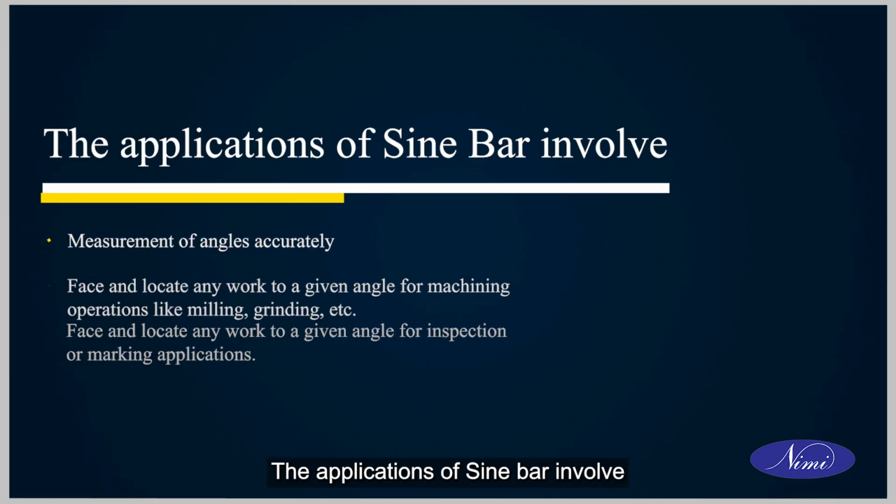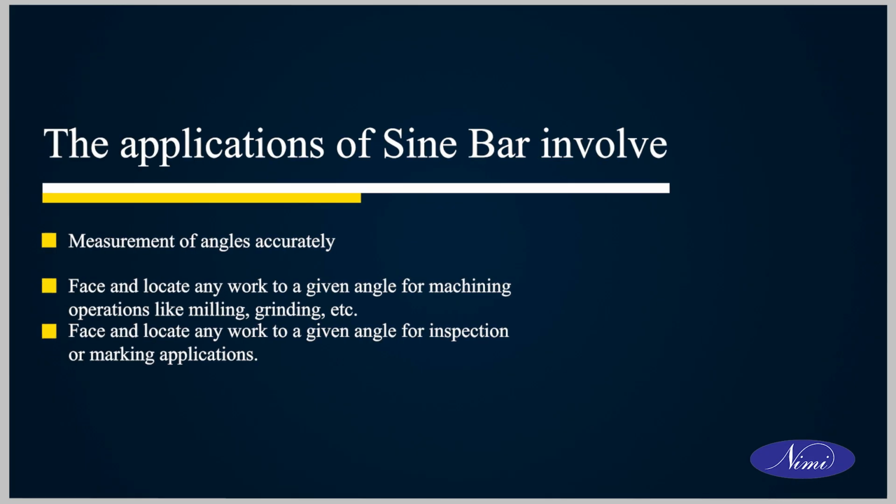The applications of sine bar involve measurement of angles accurately, face and locate any work to a given angle for machining operations like milling, grinding, etc. Face and locate any work to a given angle for inspection or marking applications.